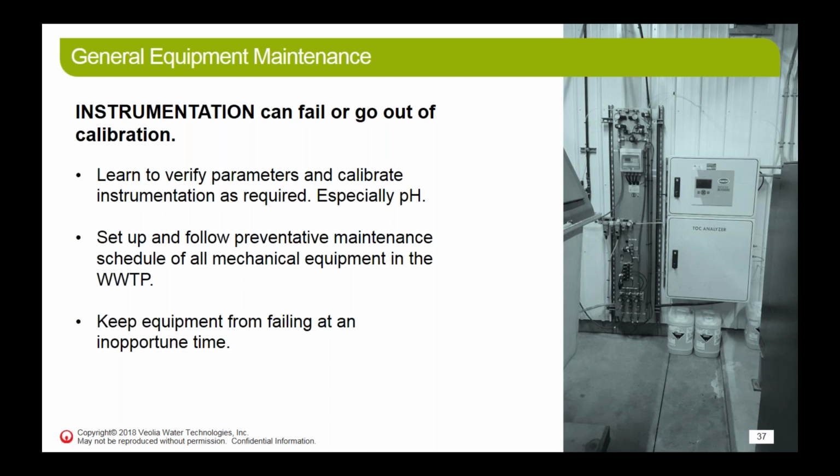So set up procedures to do preventative maintenance on all your equipment, whether it's a pump, whether it's a pH meter, whether it's a valve. Make sure that you do your preventative maintenance on these items, so you don't run into somebody calling you at midnight on Saturday night to come in because something's failed. That's the most important thing.